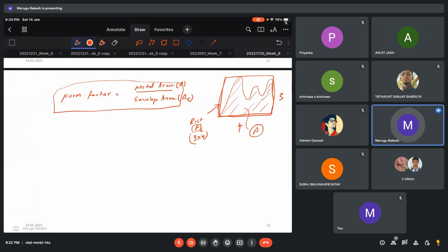If there are no questions, others can leave. Sir, regarding the center line average, you just told that if only the distance between the maximum peak and minimum value is given, then it is divided by 4.